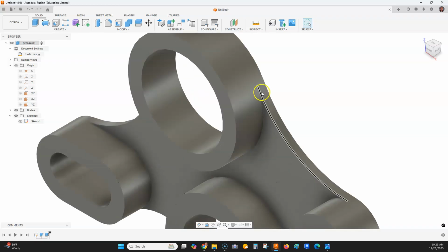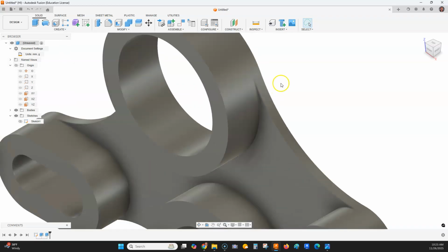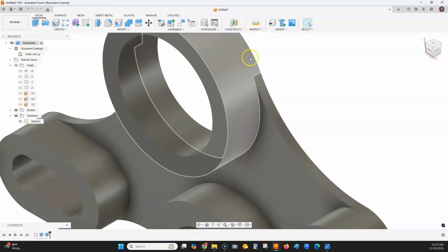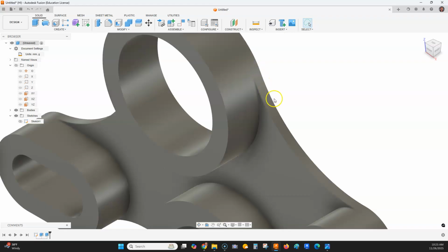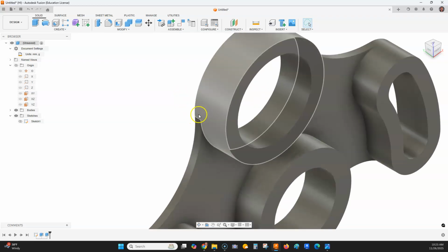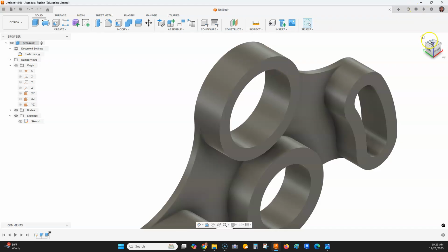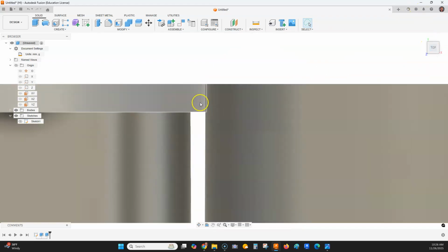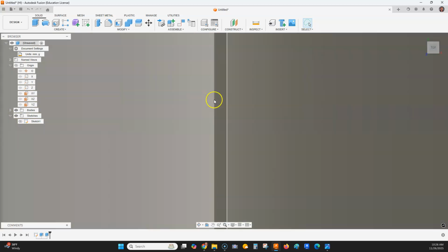One thing I want you to notice is this tangency goes nice and right up to the edge. If a marble rolled off of this, it would not hit a bump right here. It would just go straight down. That's real nice and smooth on both sides. You will see a line here signifying where this curve rests into this curve, but you would not necessarily have a bump. I don't see a little ridge in here or something like that. Maybe there might be a little one in here, but I don't really see too much of a place for me to rest my mouse. I think it would just come right down on that ridge.